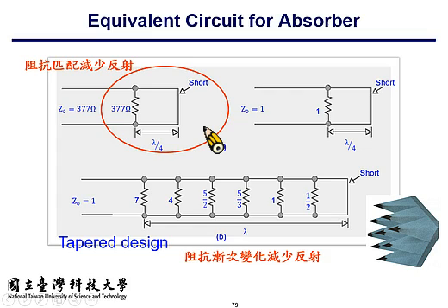Unfortunately, the Salisbury screen is a narrow-band structure. So it's only valid for one frequency, and it's only valid for normal incidence. So if you have an oblique incidence, if the wave is coming not from the front but at an oblique incident angle, then the Salisbury screen is not that effective.